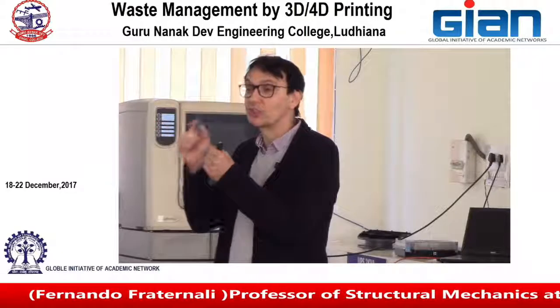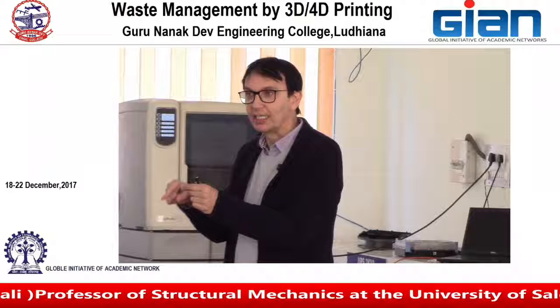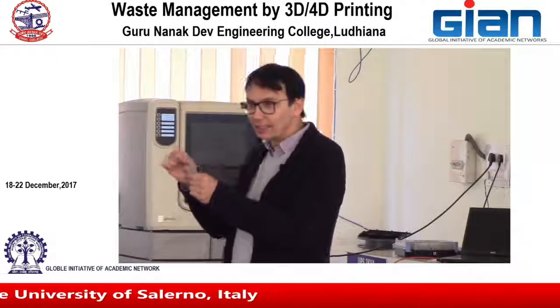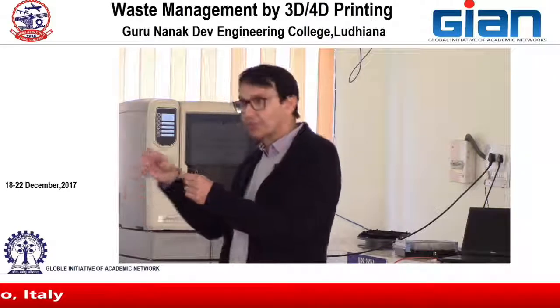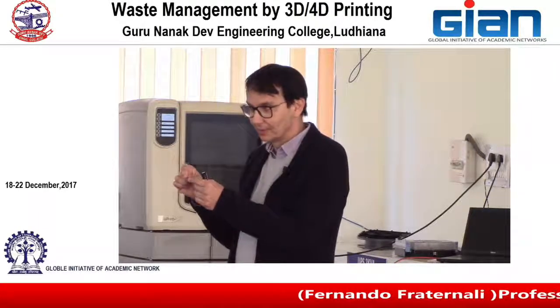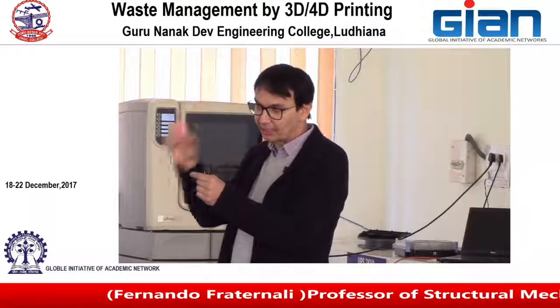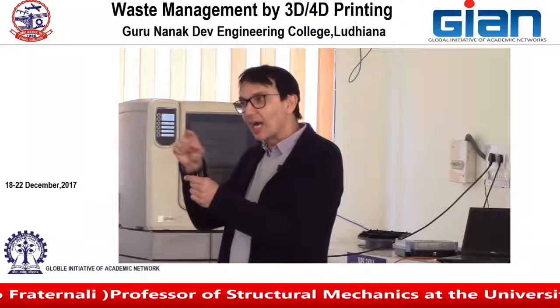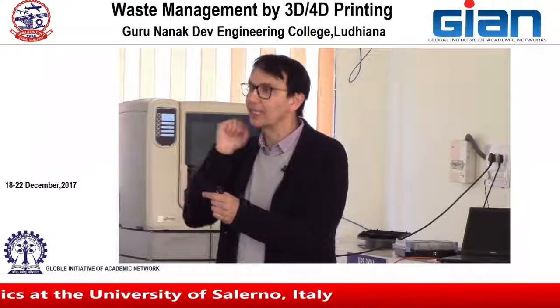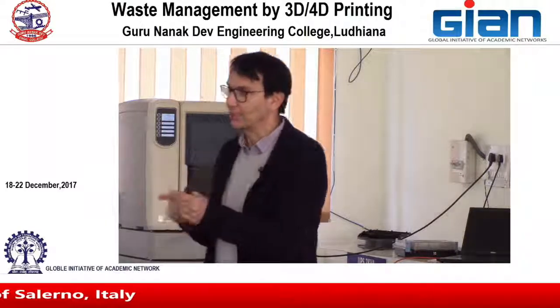This is the epsilon neighborhood of the killed element, okay? You take that volume or area, divide by 2 epsilon, and multiply by the fracture toughness. And this is the energy that you have spent to kill that element.